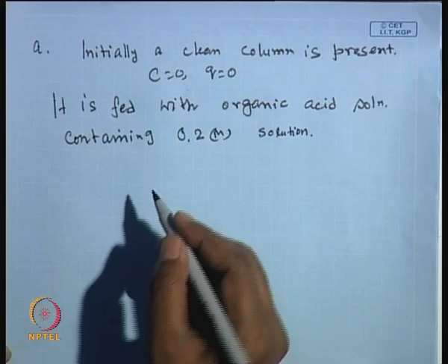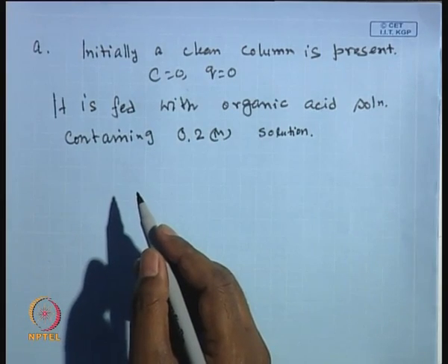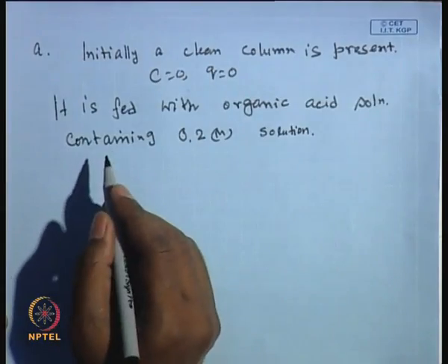Okay. You have a pump to pump the liquid through the column. By setting the pump, you can set the superficial velocity of the liquid front moving into the column. So, basically the superficial velocity will be an operating condition. The velocity of the liquid in the column is given as 5 centimeter per minute.